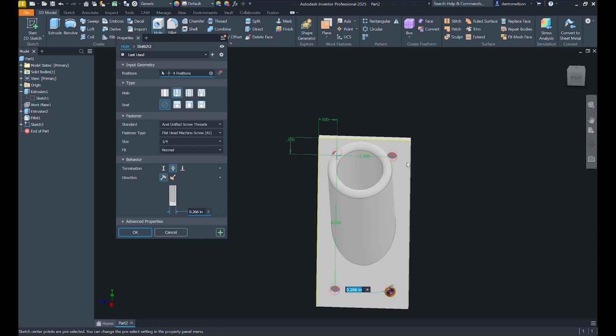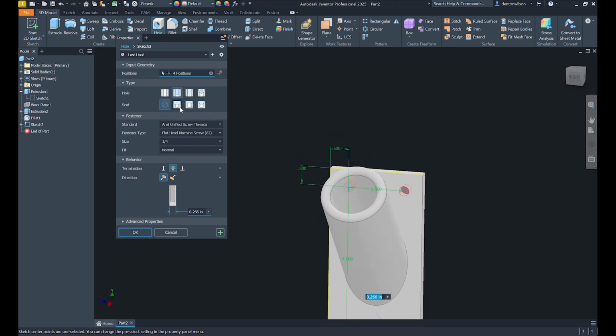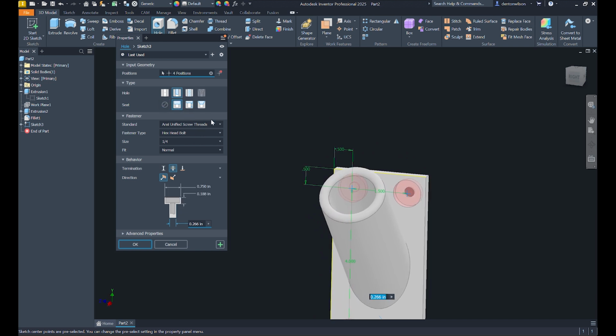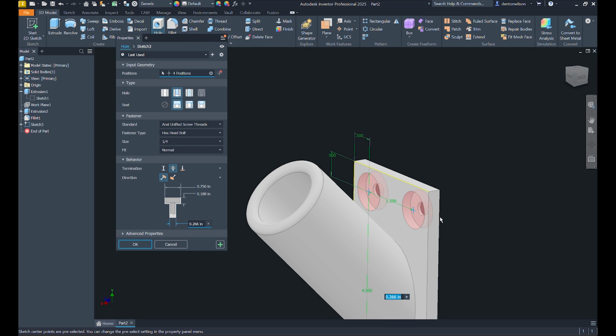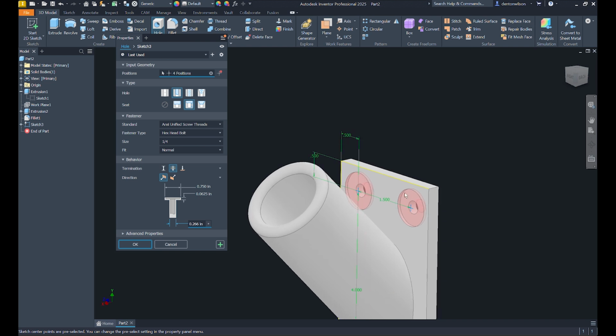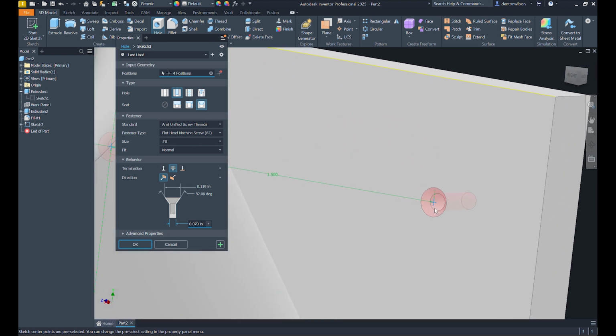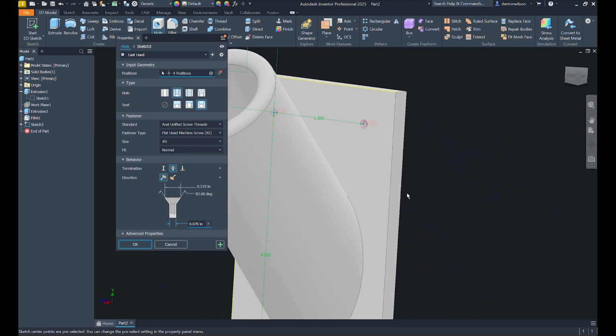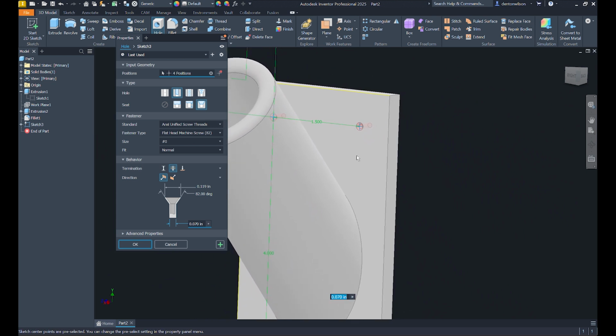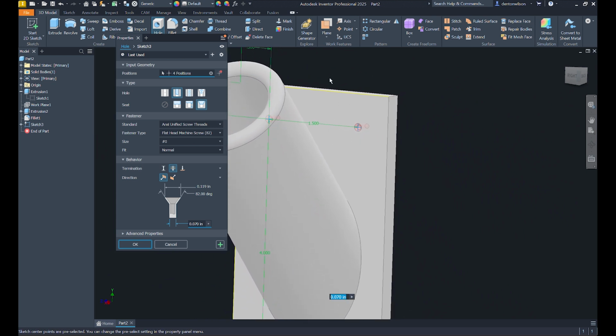And then for the seat, you can do none, which is by default. You can do a counterbore, which would be deep enough for like the actual bolt head. And then you can do spot face, which would be more for just like a washer. And then there's countersunk, which is what we're going to be using today. That's where it's actually sunk down at an angle for machine screws that have a flat head on top and are angled.